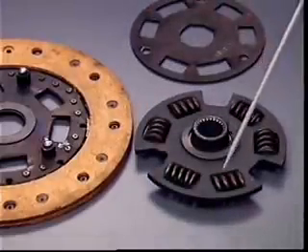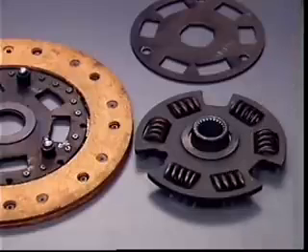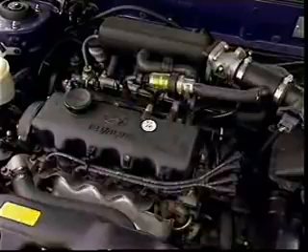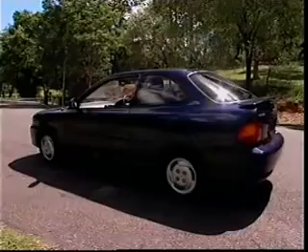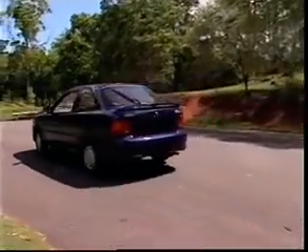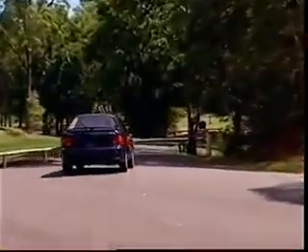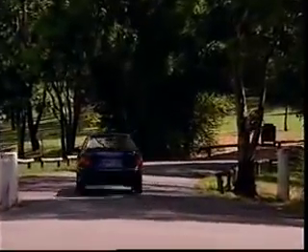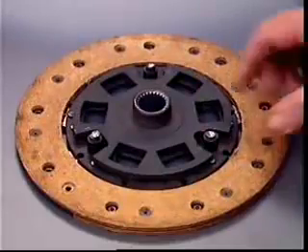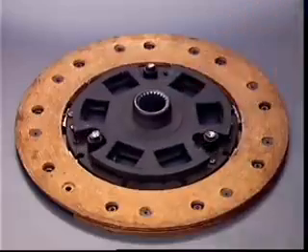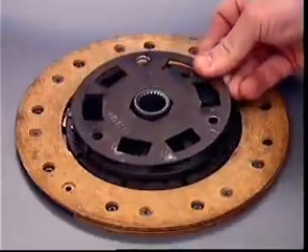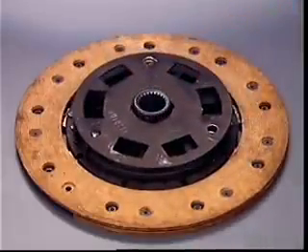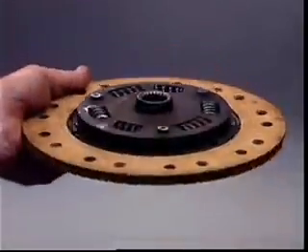Drive is transmitted from the disc to the hub through heavy torsional coil springs or rubber blocks. This spring hub arrangement dampens torsional vibrations from the engine. It also absorbs shock loads imposed on the driveline by sudden or violent clutch engagement. Stops limit the radial movement of the hub against the spring force. A molded friction washer between the hub and spring retaining plate also acts as a dampener.